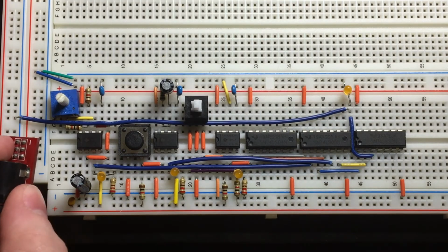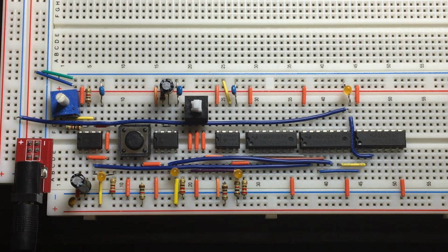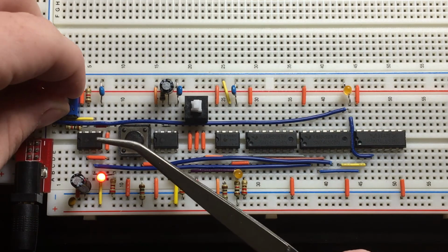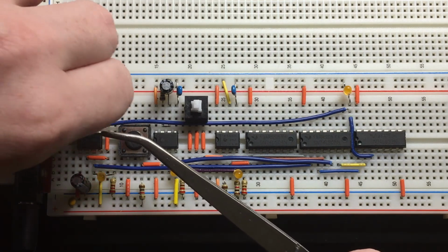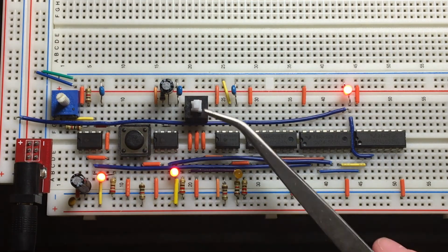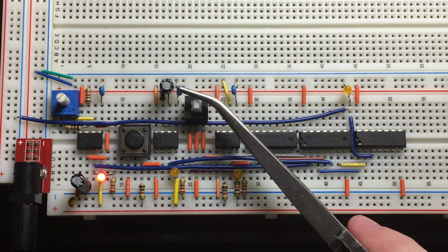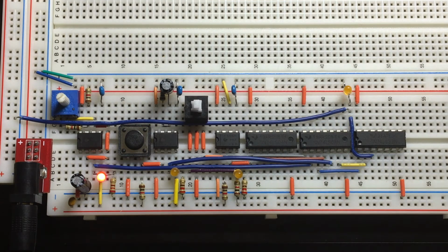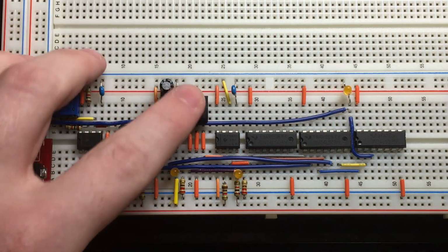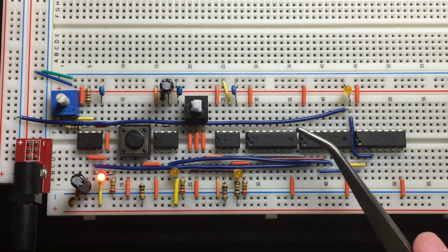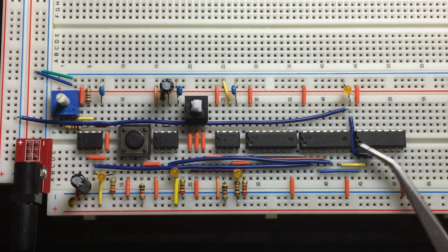So the next part of the Chump build is the Ben Eater clock. It basically has an astable pulse, which can be changed in speed to be slower or faster. A monostable pulse, which is a button that has a fixed value of how long it stays on based off of this capacitor, and a bistable, which will change from one to the other on this LED. And then this is all combined through these three different logic gates to create our output.